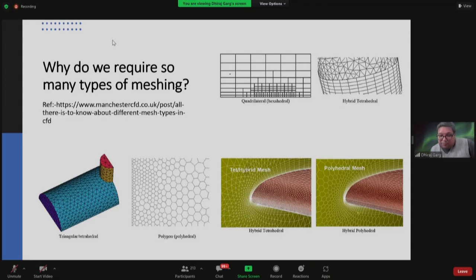Actually, the purpose of my talk was to make you aware that these things can be done, and not as to how to do it exactly. So for greater detail, I would suggest anyone who is thinking of using hybrid grid better be in contact with the FOSSEE team, and they would be happy to help you out. So if you want to use unstructured grid, what you can do is use Salome or make a mesh in ANSYS. Then you can import it in OpenFOAM. That you can do. Okay, sir.